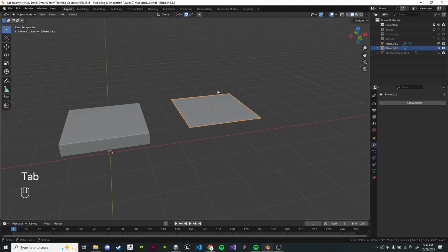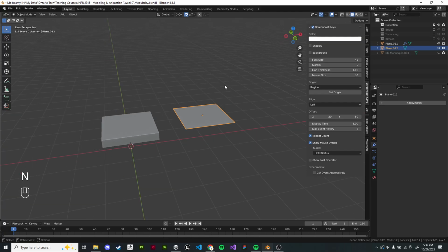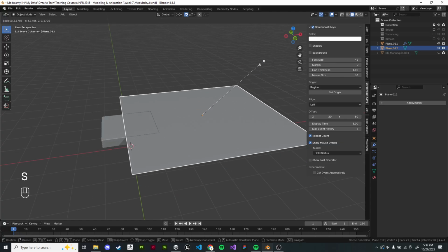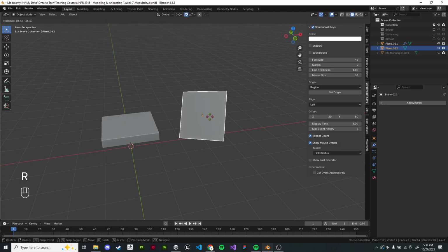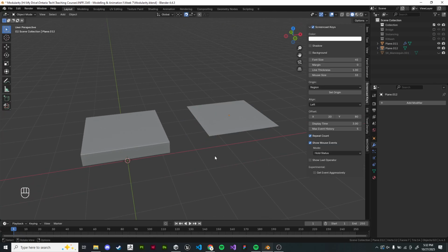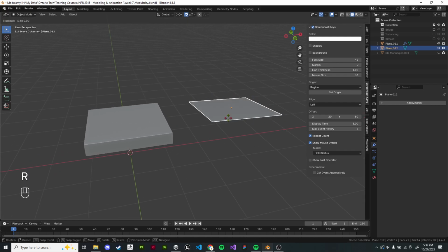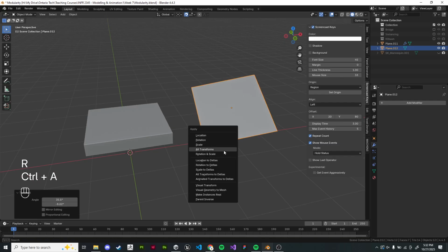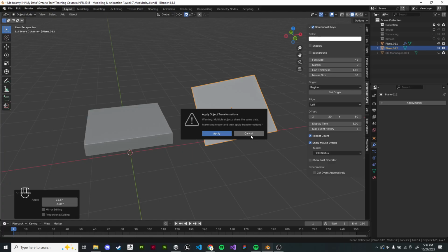Other things that it won't copy are object-based scaling and rotation. So I can still rotate this around in object mode, same with scale, and it won't affect the other mesh, right? Because I'm editing in object mode, not edit mode for the mesh itself. So we can build different pieces with our Legos here. Yep. So if you apply the modifier or the rotation and scale, would that also affect the other one? Exactly. So if I was to rotate this and then hit apply, it will actually yell at me. Because it knows that you probably don't mean to mess up all of the other things instancing this model.